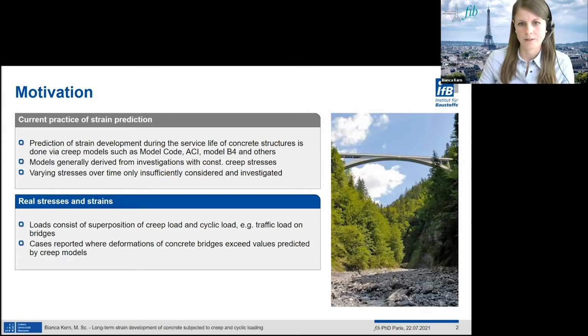Even though in reality there aren't only constant creep loads, the real loads consist of superimposed creep and cyclic loads, for example, traffic loads on bridges. And that's a problem because it's supposed that the superposition of these load types causes the measured deformations of various reinforced concrete and pre-stressed concrete bridges to exceed values predicted by creep models.